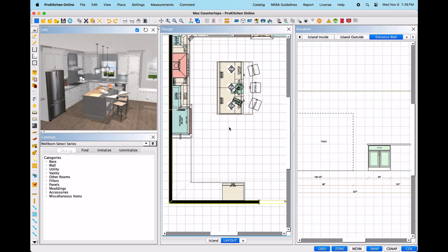The last of the four additional edit tools found on the lines of the countertop is Radius End. This tool will add a curve to the selected line, creating a rounded edge to the countertop. Once this option has been selected with a left click, move the mouse and you will see a triangular outline either going inwards, creating a concave curve, or outward, which will create a convex curve to the countertop. Move the mouse in the direction you wish to create the rounded edge.